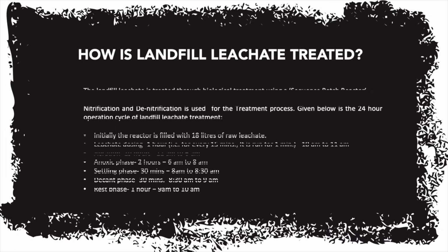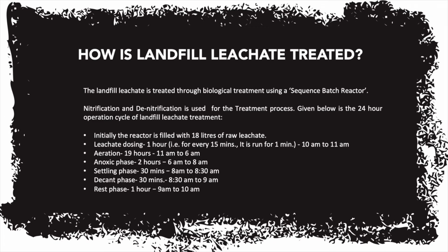How is landfill leachate treated? The landfill leachate is treated through a biological treatment using a sequencing batch reactor. Nitrification and denitrification are used during the treatment process. This is done over a 24-hour operation cycle for the landfill leachate treatment.